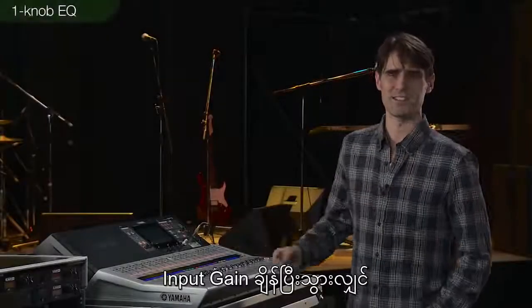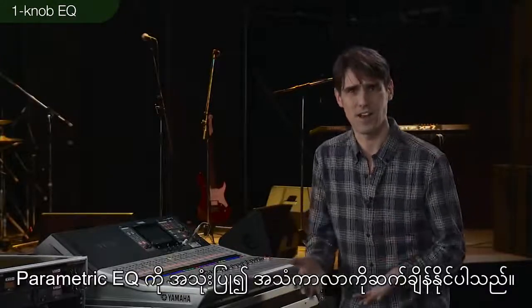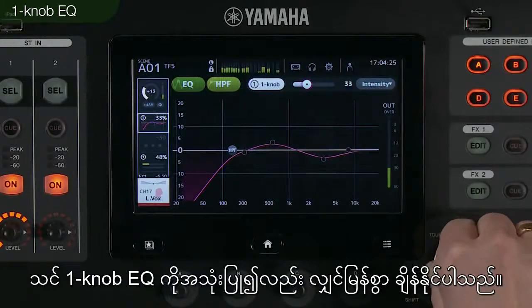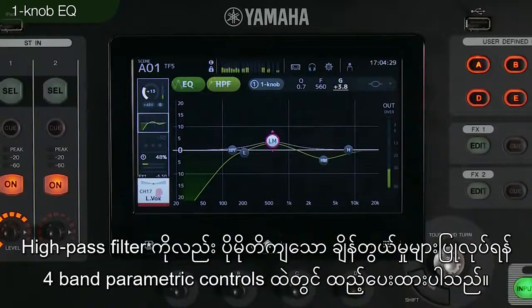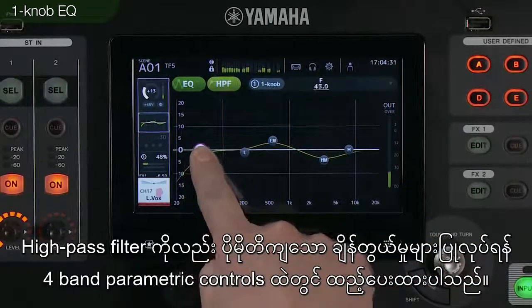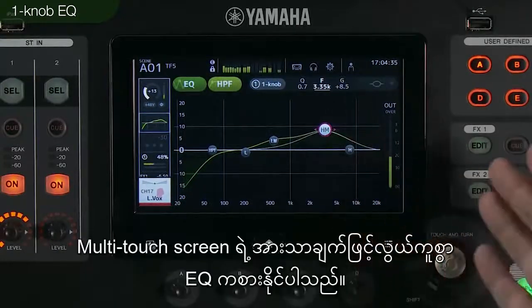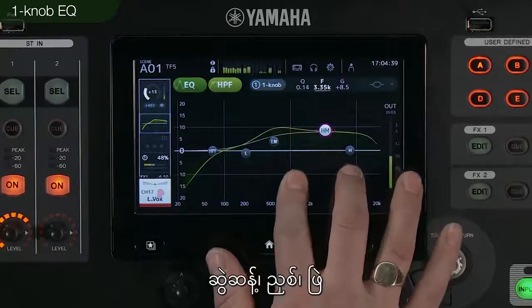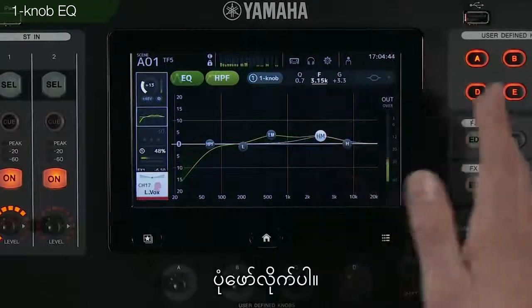Once the input gain is set, the parametric EQ can be used to shape the tonal color of the sound. You can use the one knob EQ for quick adjustment, or the full 4-band parametric controls with additional high-pass filter for detailed tweaking. With a multi-touch screen, adjusting EQ is a breeze. Stretch, squeeze, drag, sculpt that sound.